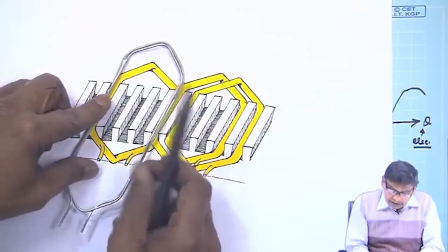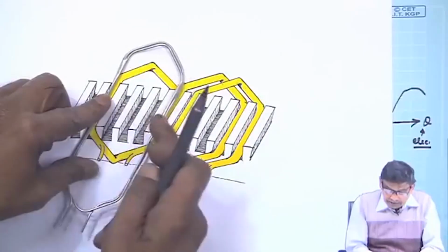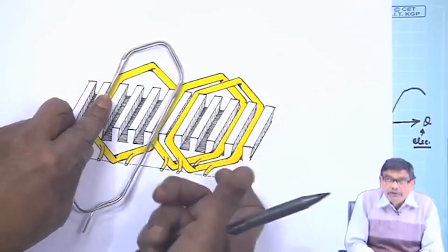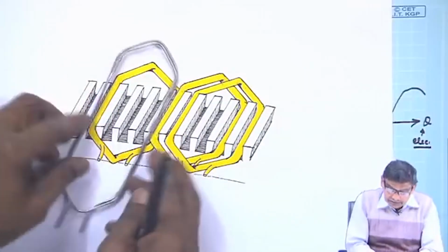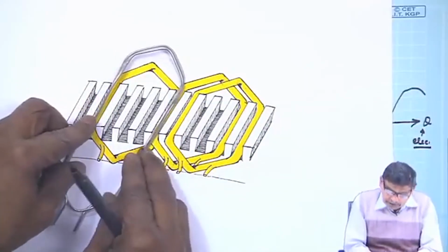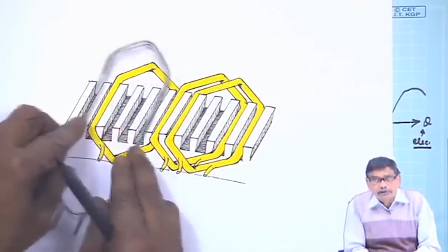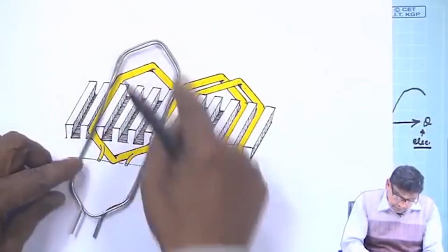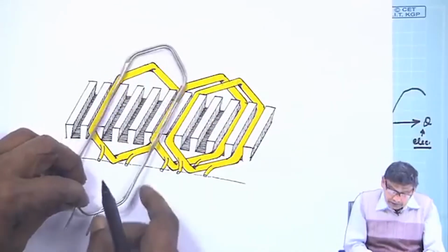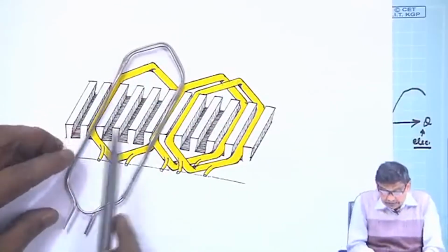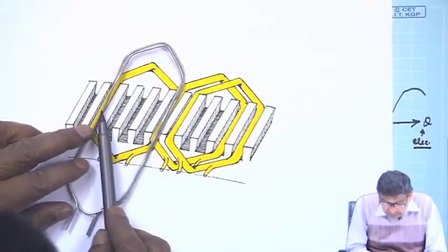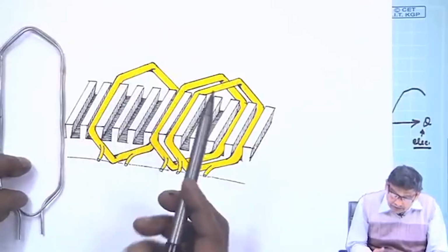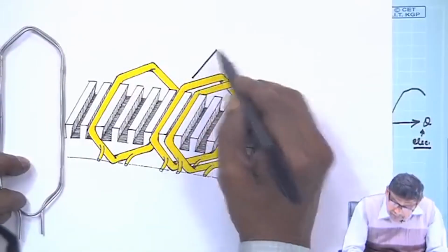Then only, the velocity of these two coil sides cannot be different, because the rotor will be moving with some speed and they are fixed in space. Therefore, they will also move with the same velocity. So, it is a two turn coil with two terminals available, but the only thing you have to see is this distance, this to this distance, that is called the coil span.